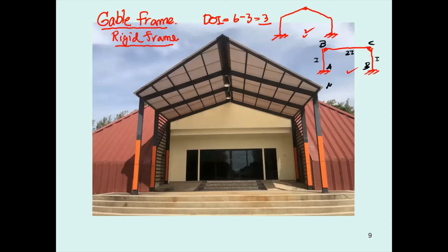If you go back to the slope deflection and you would like to determine the moment M sub AB, it requires you to use 2EI over L times 2 theta A plus theta B minus 3 delta over L, or 6, and then plus the fixed end moment AB.